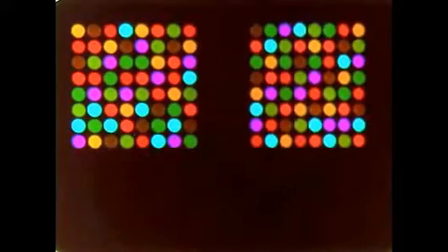We carry out this process for every element in the mesh, so that we now have a stiffness matrix for each one. The important step now is to combine all these individual matrices into a single large matrix representing the stiffness of the whole system.